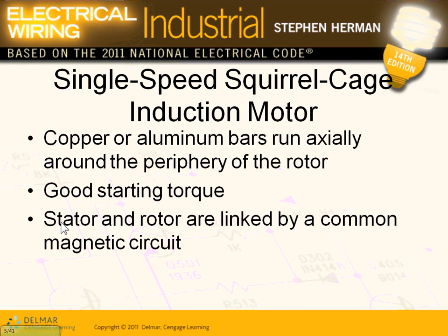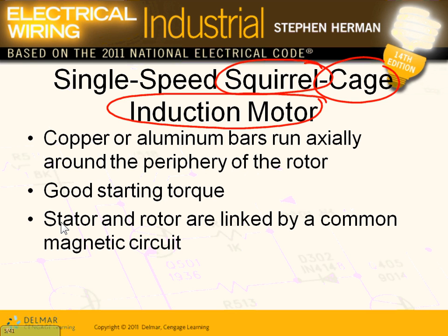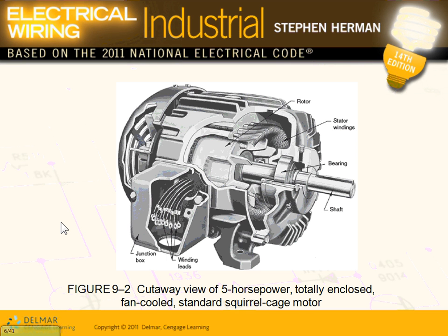The single most important motor that you're going to encounter in the industry, in the construction industry, guys, is called the induction motor, or squirrel cage induction motor. The cheapest, easiest way of making a motor is a squirrel cage induction motor. And you guys are very familiar with this. We have them in our lab. What they do is they have bars over here, the rotor, shorted bars. They have bearings over here, you can see mounted on the bearings, and they rotate inside a coil. The cheapest, easiest way of making it.